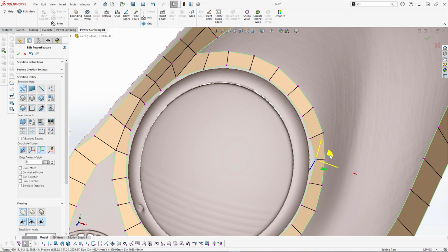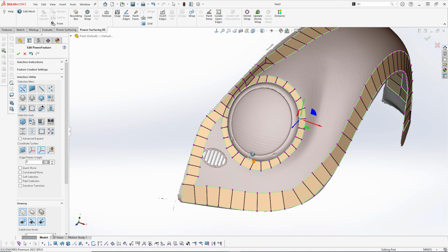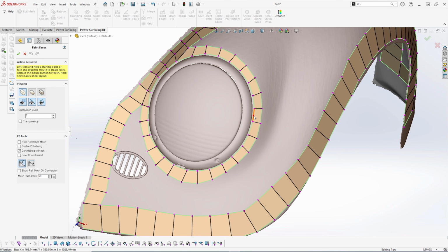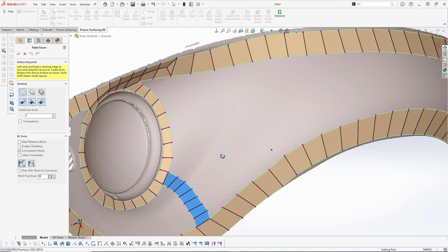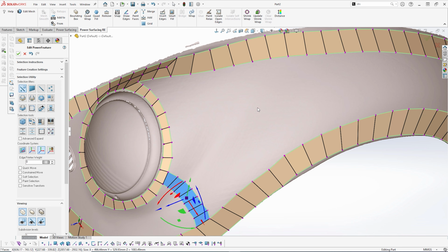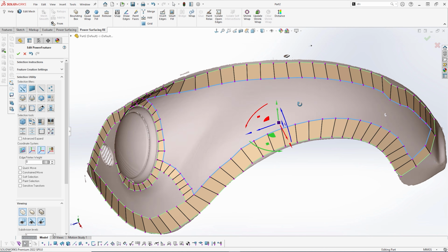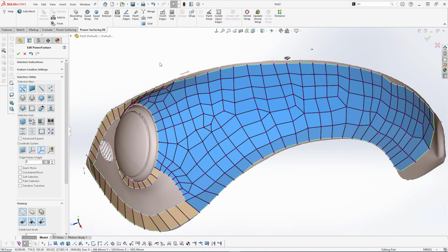Okay, so far that's looking pretty good. We've got all of our outside edges. The next step is we're going to do the rest of the face. Now again, to make our lives quicker and easier, rather than just painting all of the faces, we have the Smart Fill command. Really simple to use. Quick double click and we can select the outside boundary, go into the Smart Fill command, and you can see within a few seconds it fills in that boundary.